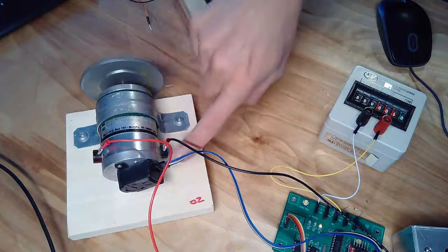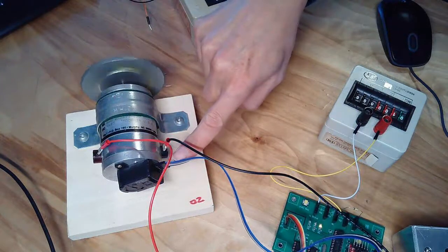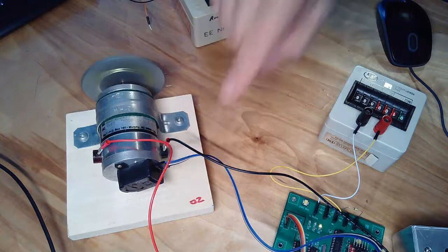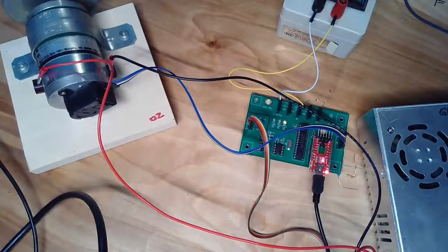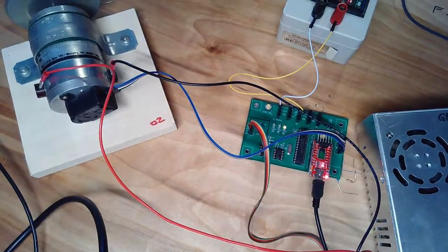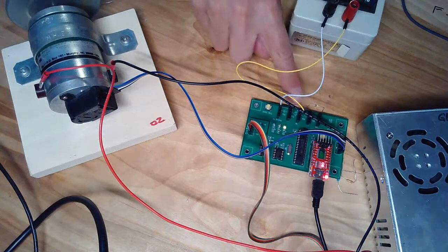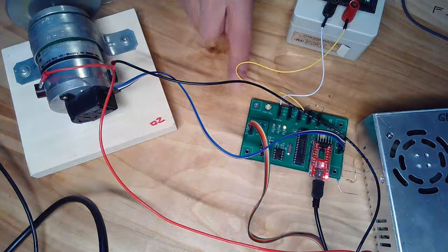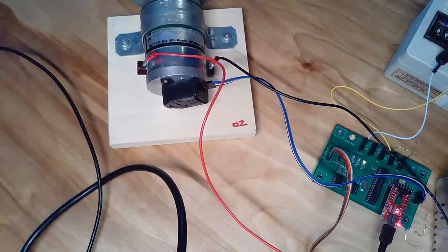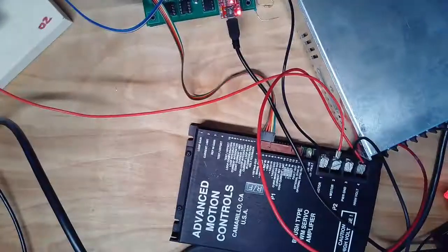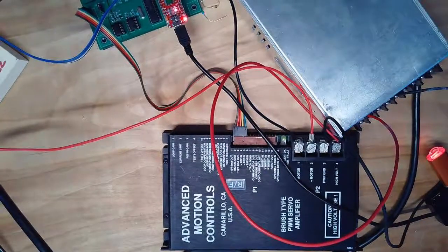The optical encoder, this guy right here, outputs 250 pulses per rotation. That goes to a little PIC board. The PIC board just counts pulses and measures pulses per second, computes the speed, has an op amp circuit right here. That op amp circuit then amplifies it and outputs it to the power amplifier that drives the motor.